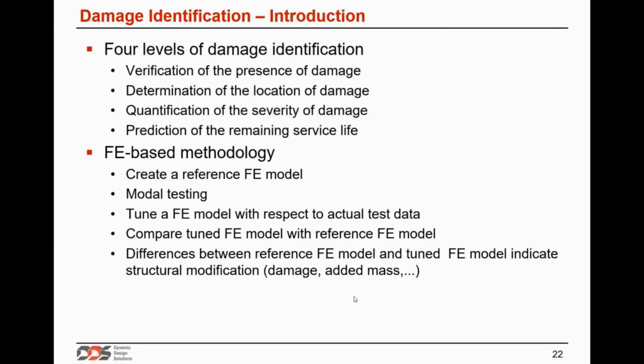From an updated finite element model that has included the damage, so it represents the actual damaged structure, this allows you to also update the prediction of service life compared to the beginning of the operation of a bridge, for example.